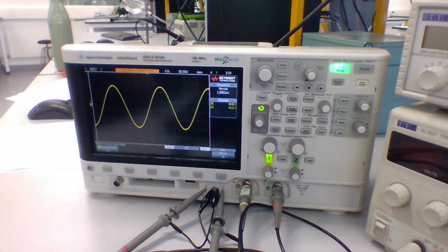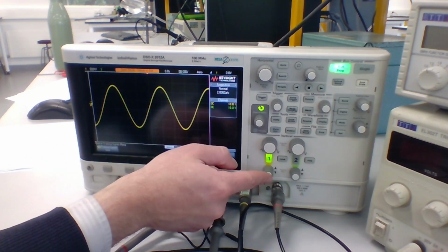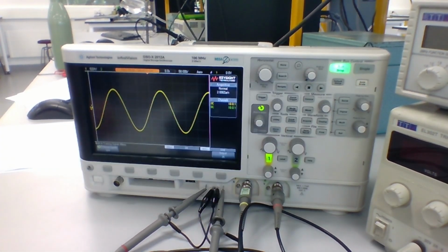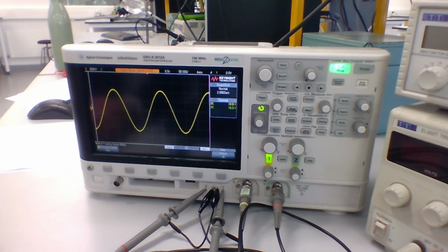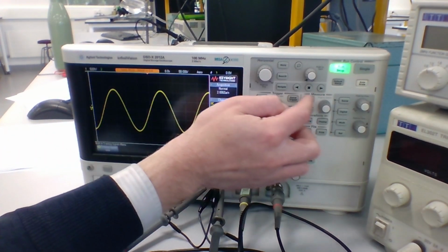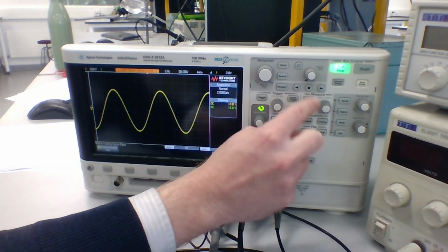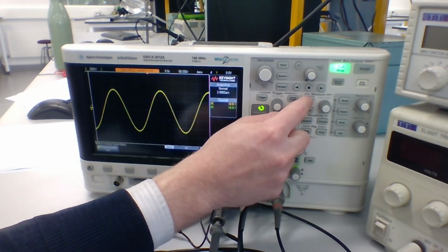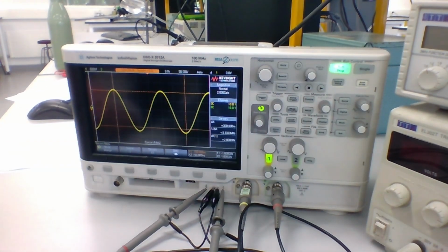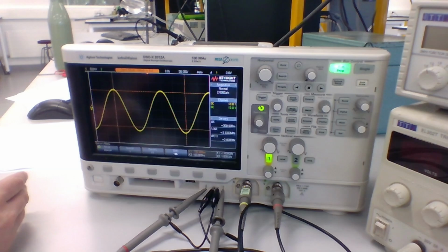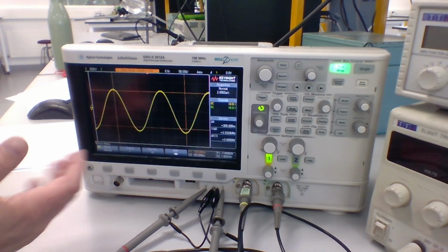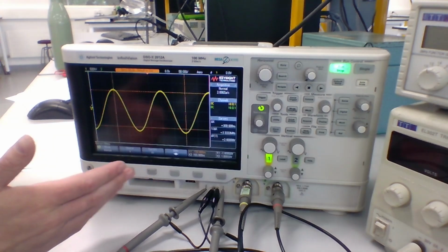The other way we can take measurements on this oscilloscope, I'm just going to set this back to 0, is we can use the cursors. So our oscilloscope has cursors we can place on the screen, and we can move those around to take measurements. To do that, we first of all need to turn the cursors on. There's a button here. You'll notice there's a measurement section on the front panel. We press the cursors button. That brings up cursors on the screen. We can then move these cursors around and measure what the difference is between these cursors, and thus measure what we're seeing on the screen.